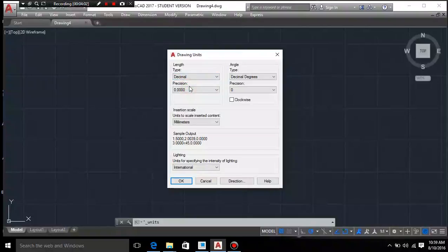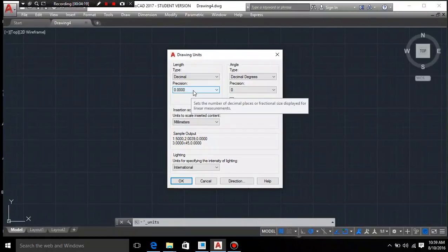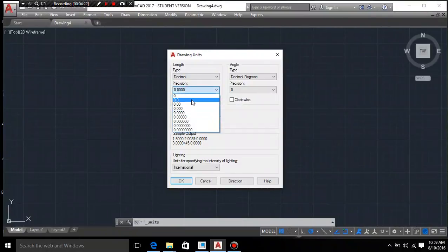The next one is precision, and the precision is just talking about how precise we want these millimeters to be. Right now we're set up for 10,000ths of a millimeter, which is pretty fine. We're not going to get into stuff like that. So what we will look at is probably moving this down to just a 1 decimal place digit. If it was to say 41.5, I know there's one assignment that has a 41.5. If it did say 41.25, then we'd have to go to 2 digits. So I think that we can get away with right now just going with 1 digit. We could always change that if we had to.